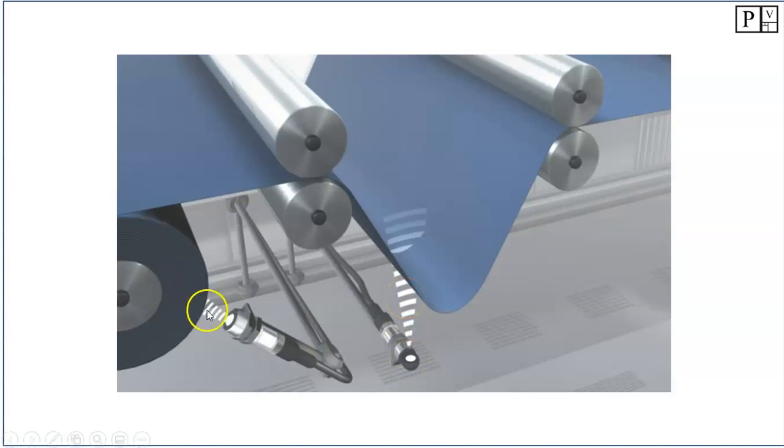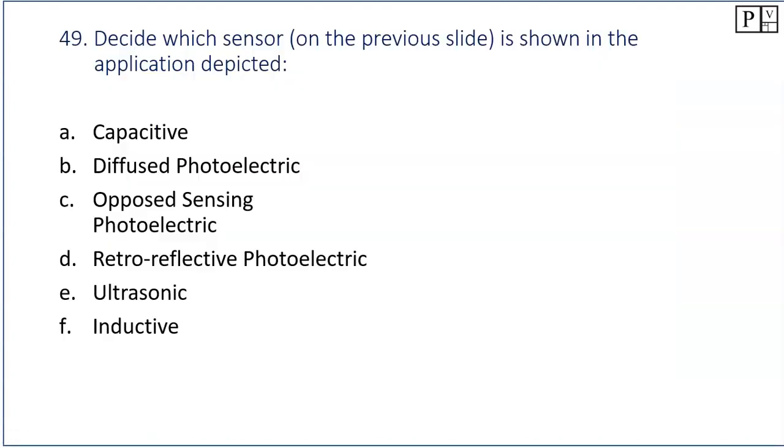It's being used to look at probably an analog output here for the size of the actual roll. So when the roll is done, then the sensor will give a different output. For this guy, we're probably looking for a static value coming out, like a certain range from the 4 to 20 milliamp of the ultrasonic sensor, to tell us that we have that dip, and we're not going to put too much tension on the fabric or on the paper there. So that one again is an ultrasonic sensor.